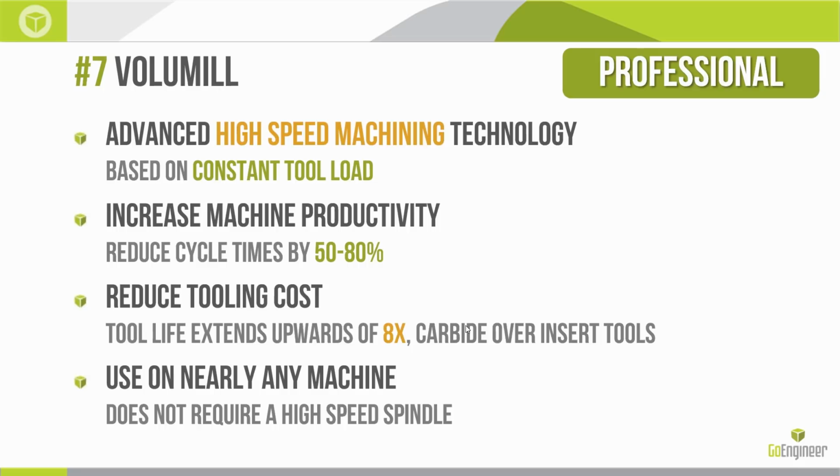I think 50 to 80% is actually conservative. It varies case by case. It also reduces tooling costs by extending tool life. This is a toolpath technology that's easier on the tools, easier on the machine, and yet, it sounds crazy, but it actually improves cycle time.